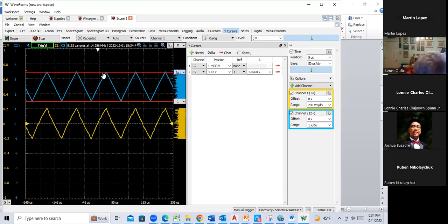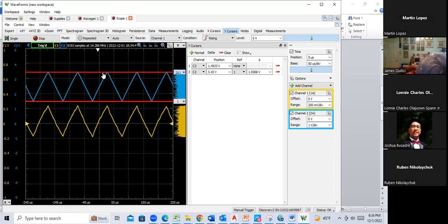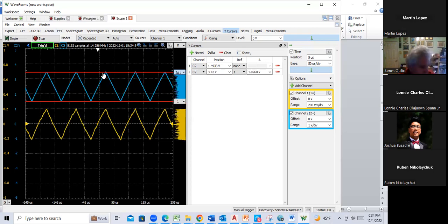Okay. So anyway, finally, step 11, it says, do a frequency sweep and find the lower minus 3 dB frequency. So we want to find out where the amplifier's high pass, it's on the low end, but it's a high pass, where that occurs.